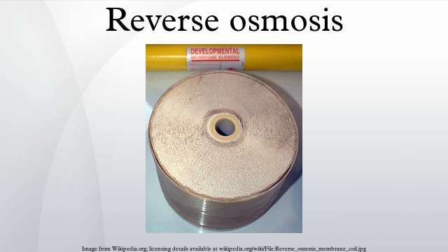Seawater reverse osmosis desalination, a membrane process, has been commercially used since the early 1970s. Its first practical use was demonstrated by Sidney Loeb from University of California at Los Angeles in Coalinga, California, and Srinivasa Sourirajan of National Research Council, Canada. Because no heating or phase changes are needed, energy requirements are low, around 3 kWh per meter 3, in comparison to other processes of desalination, but are still much higher than those required for other forms of water supply, including reverse osmosis treatment of wastewater, at 0.1 to 1 kWh per meter 3.